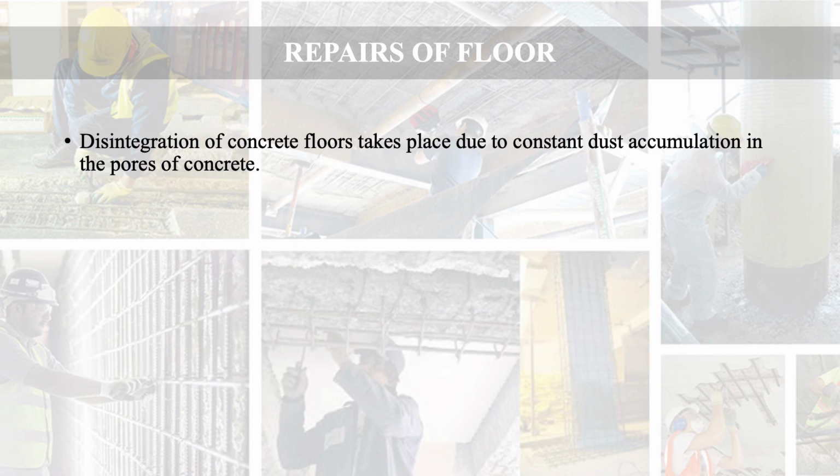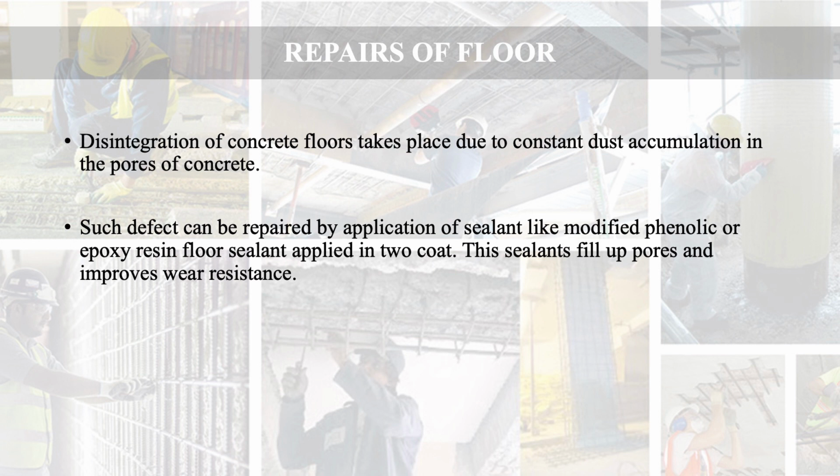Disintegration of concrete floors takes place due to constant dust accumulation in the pores of concrete. Such defect can be repaired by application of sealant like modified phenolic or epoxy resin floor sealant applied in 2 coats. This sealant fills up pores and improves wear resistance.